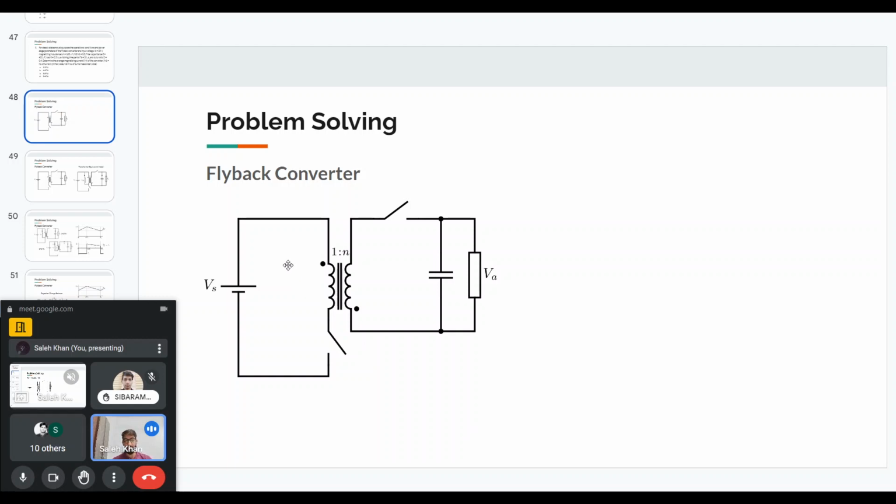By having isolation in the converter, there is no direct connection, so that provides us that safety option. It can also help if we want to reduce noise in the circuit, because when we are switching, if there is high frequency noise on one side of the circuit, the grounds get corrupted.